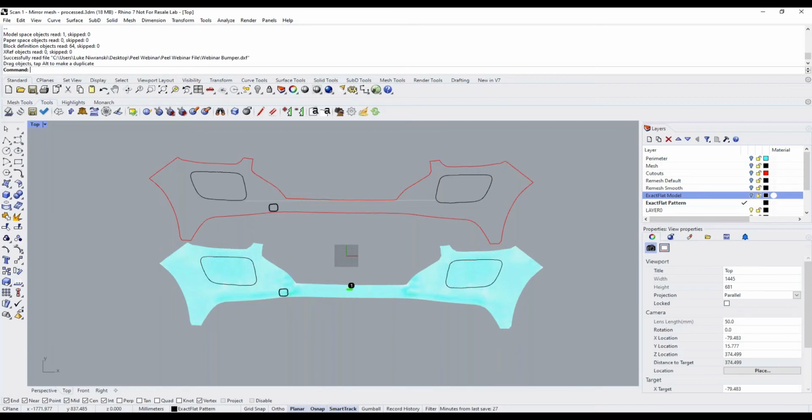So with the target strain, you're telling it how much strain you want to be applied to your part in order to get it to fit. Whereas if you're scaling it, you're having to specify a scaling factor, like scale at 99%, 98% or so. So it might not be as simple as using the global target strain, but there are alternatives if you don't want to use the global target strain.